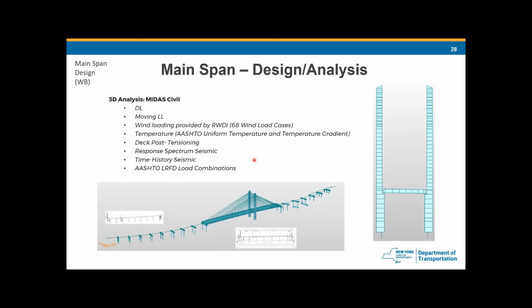And to design the main span is a complex process to capture the actual behavior of the cable-stayed bridge. We create a 3D model in Midas Civil, and we use Midas Civil to analyze dead load, live load, wind load, temperature load, post-tensioning, and seismic from response spectrum analysis and time history analysis. And all these loadings are combined according to the AASHTO LFD load combinations.